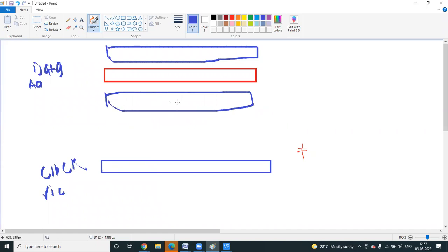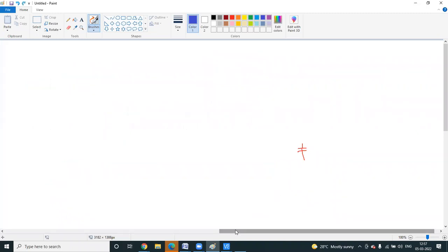So if you protect the aggressor first, and these shields are connected to a lower potential, this line will not create noise because you connected it to ground, or generally, okay, that I will tell later. So whatever noise signal is generated from here will not come through, because this is the only one causing it. Let me explain in a better way.